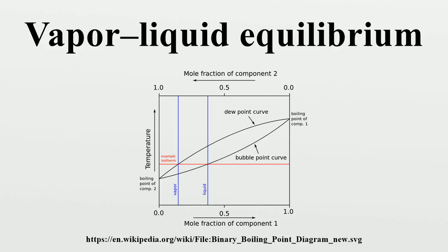The preceding equilibrium equations are typically applied for each phase individually, but the result can be plotted in a single diagram. In a binary boiling point diagram, temperature is graphed versus x1. At any given temperature where both phases are present, vapor with a certain mole fraction is in equilibrium with liquid with a certain mole fraction. The two mole fractions often differ. These vapor and liquid mole fractions are represented by 2 points on the same horizontal isotherm line.